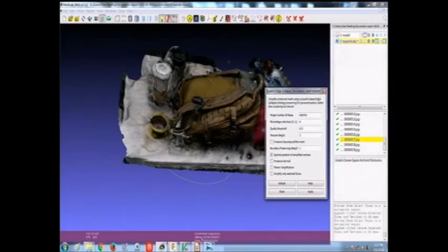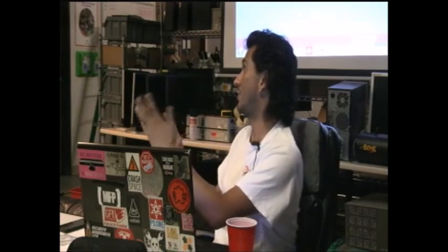We've got 800,000 faces right now, and in my research I've also realized that the human eye can hardly detect anything over 200,000 polygons. You could sit here and hit that button a few times and slowly bring down the polygon count, and you won't see anything physically change unless it's under 200,000 polygons. But most of the time, you can get away with 2,000 or 1,000 polygons. 10,000 seems like a nice mid-range. It mostly depends on how big the texture is that you're applying to the surface afterwards.